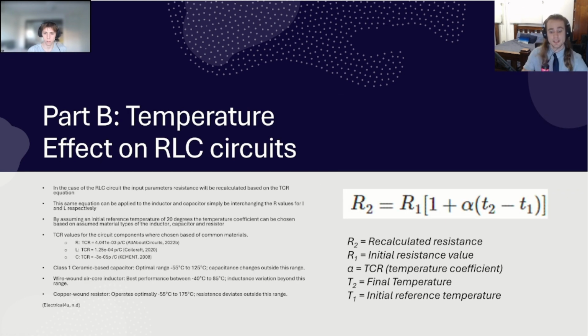When dealing with RLC circuits, temperature can affect the resistance, inductance, and capacitance of the components by using the temperature coefficient of resistance, the TCR equation. The change of RLC values can be recalculated based on a reference and final temperature. This equation applies not only to resistors, but to inductors and capacitors with a simple change of variables.